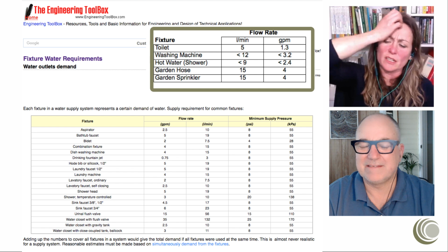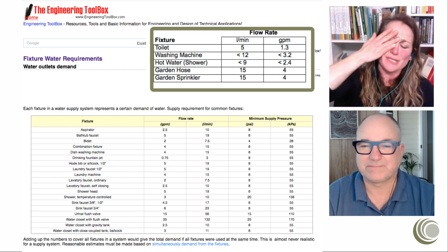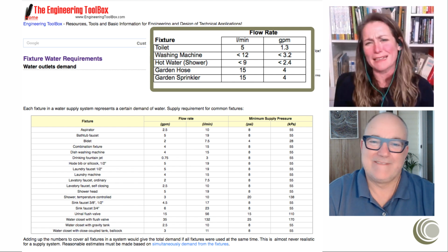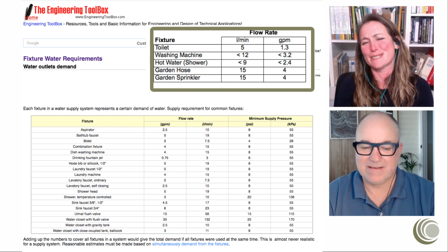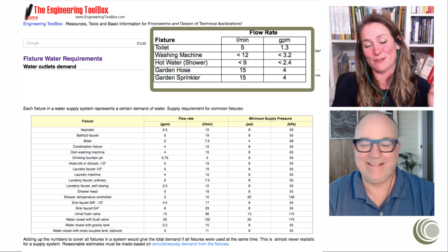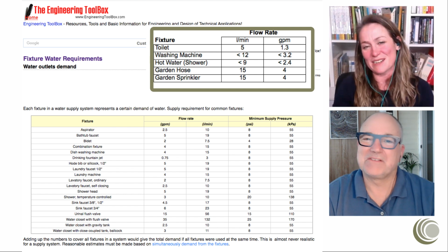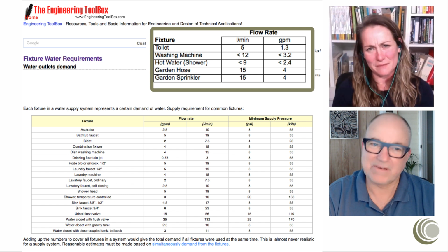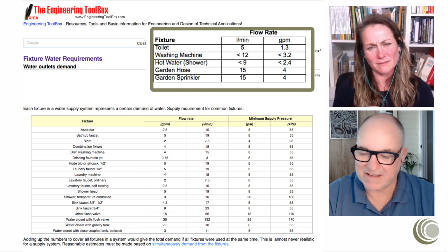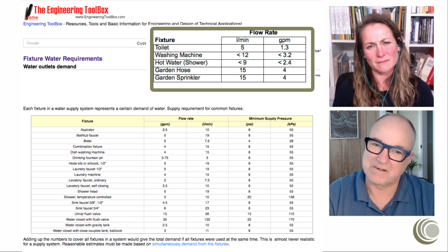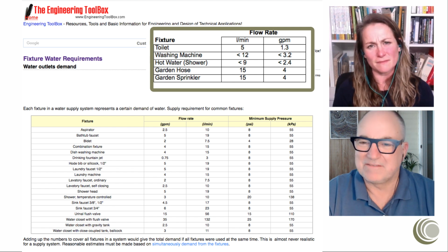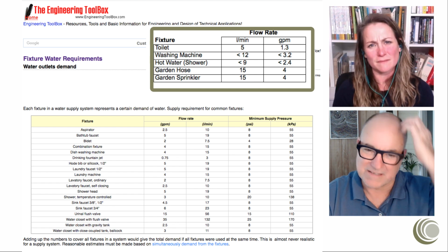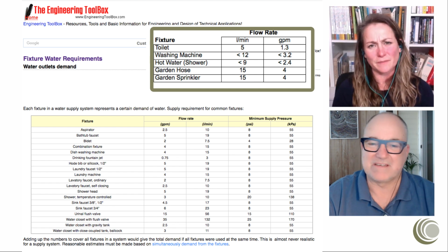I'm scratching my head, Peter, because wouldn't that mean you'd have two sets of supply lines if you had separate rainwater supply? Is that basically implying that you should have two separate plumbing systems in your house? One to supply rainwater to your tap and one to supply mains water to your tap. Well spotted, Michelle. The plumbing code was created by the water utilities who weren't keen on rainwater harvesting, and it was forcing two different systems, so that no longer applies, and you have the same system.